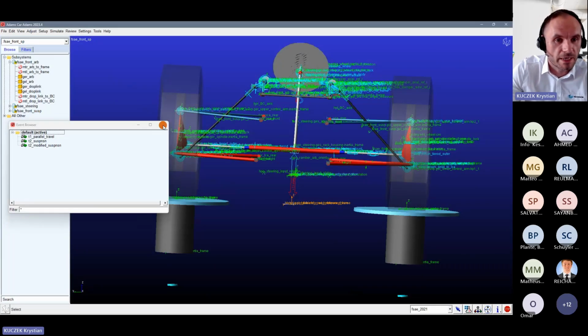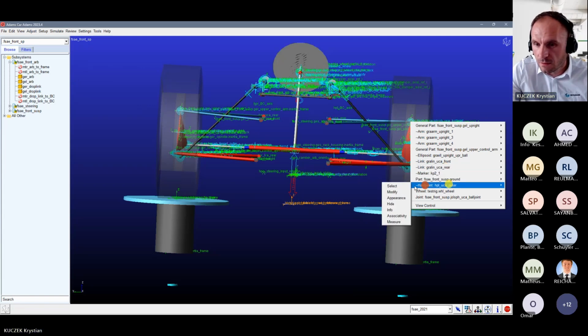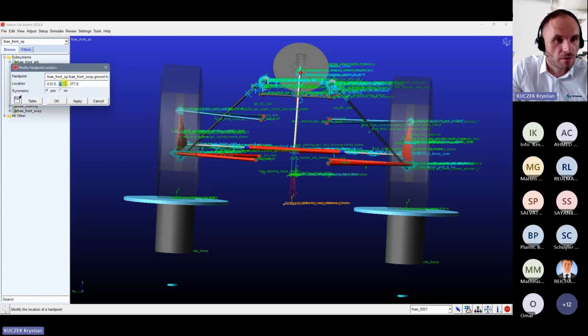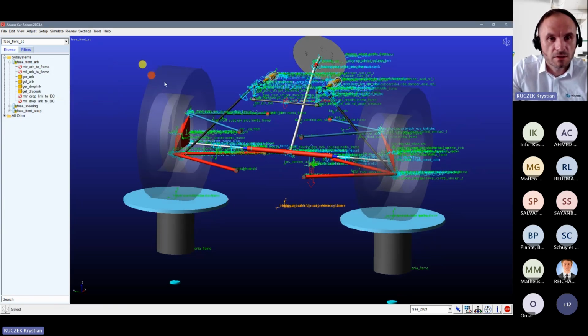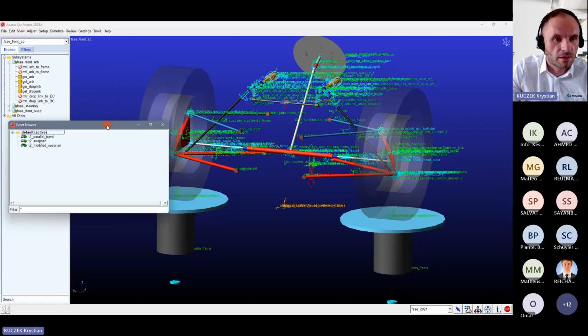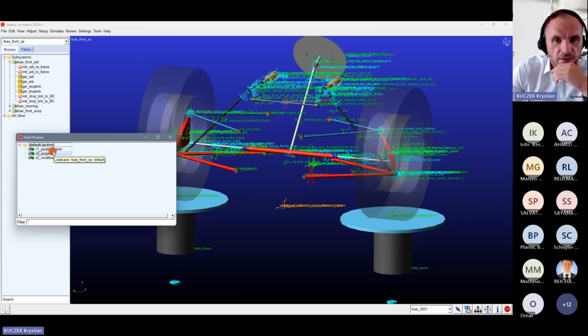We will use again the previous stage of our model, which was used for the first study, but I would like to put it again into the design position, because currently I changed it manually, and I would like to automate that and also check different results like roll center, by changing it automatically and making the Adams solver busy.